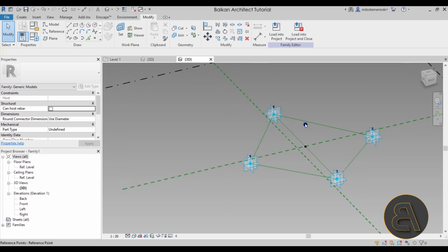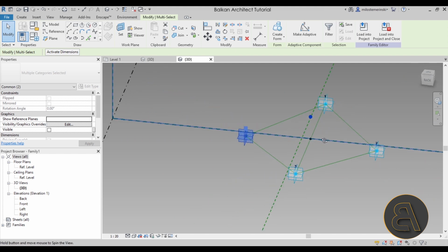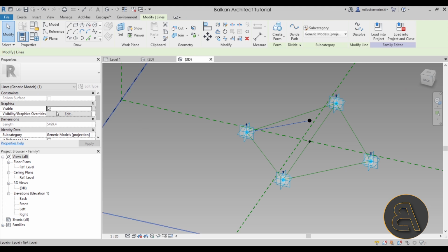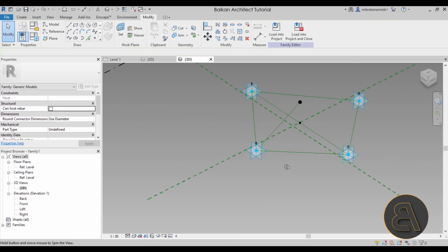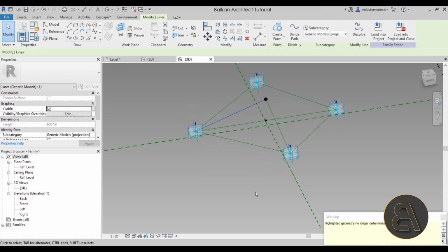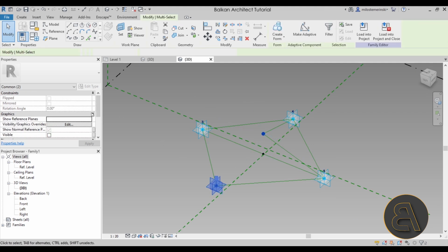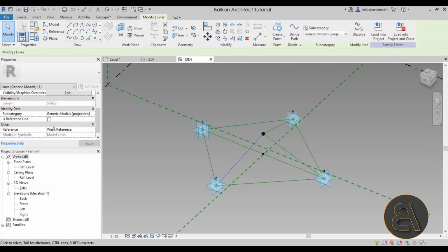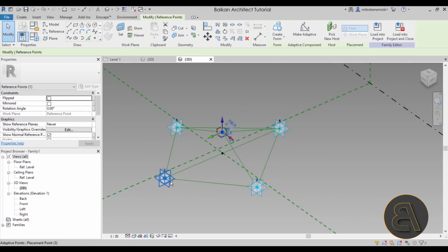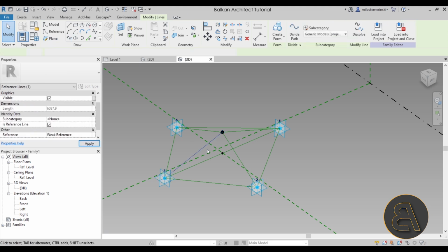Anyways, now once we have done this, we can select this point, and then let's select point 1, so have them both selected. So hold the control key, select both of these, spline through points, and then you can make it a reference as well. And then repeat that additional 3 times. Spline through points is reference, ignore the warnings because, well, it's safer that way. Just kidding. Anyways, we have just a few more. Holding the control key, spline through points is reference, and we're done.